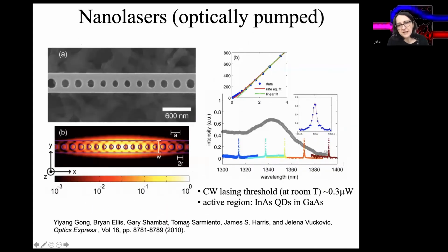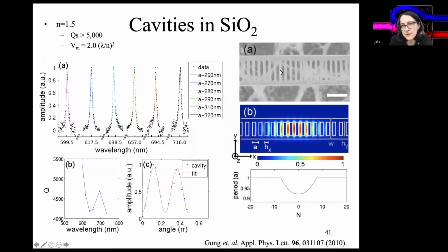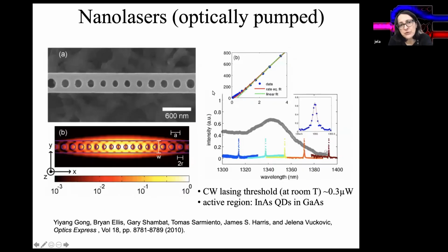Of course, you can make it in a variety of other materials. You have one dimension in which you are introducing these distributed Bragg reflectors. Often you will see people make these types of DBRs where you're just etching rectangular shapes. This was adopted from a paper that I'll show you later from Caltech, Oscar Painter's group. But you can also introduce a resonator by making circular holes along the axis.